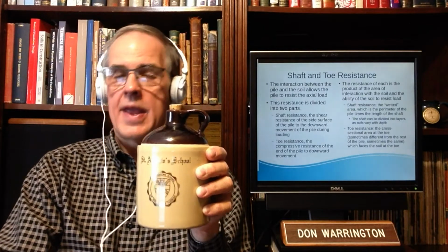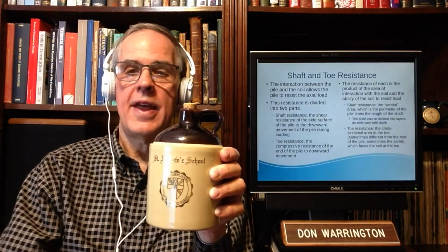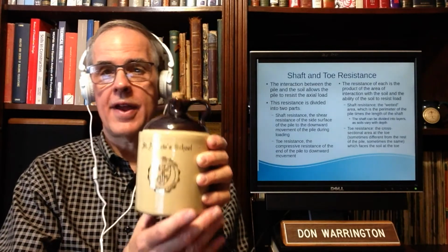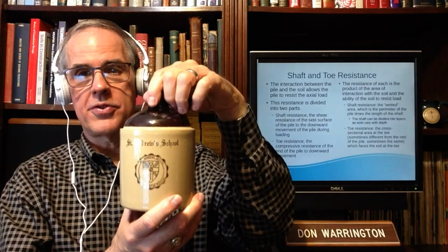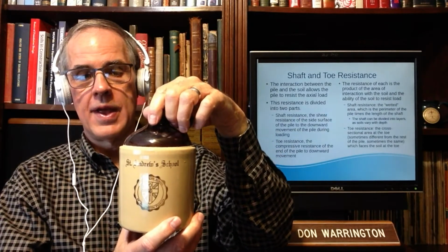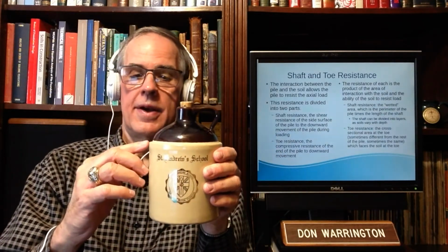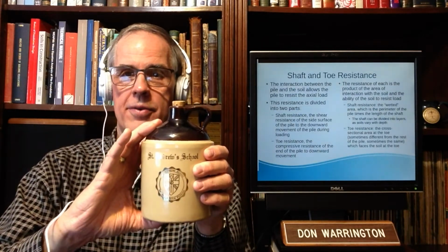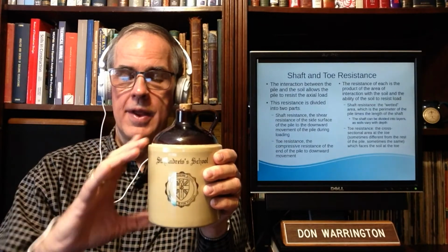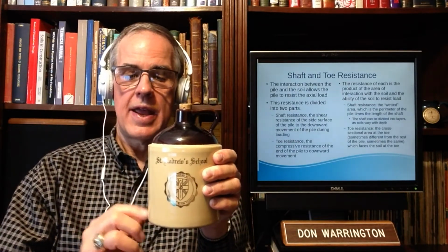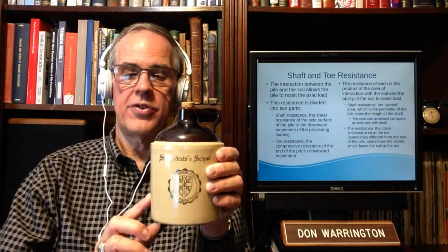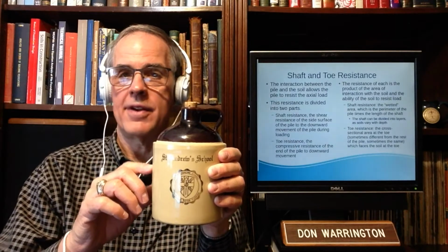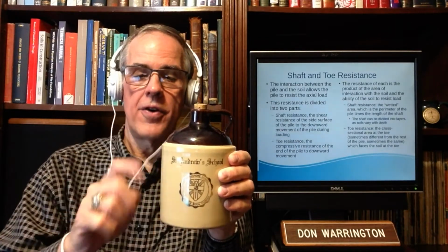Now, it is important to understand that concept. Also important to understand is the fact that as I load this, it is going to go further down. This is going to have axial flexibility, and that's hard to see with this, but it does. Basically, these are resisting springs with a limiting resistance. In other words, they're elastoplastic. And as I go down further,